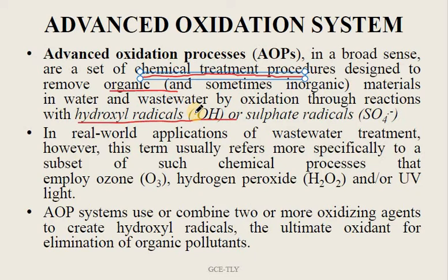Okay, so OH radical or sulfate radical, SO4 dot minus. In real-world application of wastewater treatment, however, this term usually refers more specifically to a subset of such chemical processes that employ ozone, hydrogen peroxide, and/or UV light.